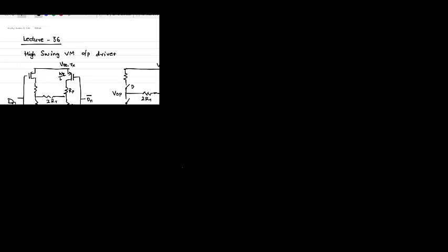And these switches are Dn, Dn bar, then Dn bar and Dn. In the actual output driver, the PMOS and NMOS are connected by the same control because they are complementary. So at a time only one will be on, and the output swing here will be VOP minus VON. Whenever it is on, it will be plus minus VDD Tx by 2.